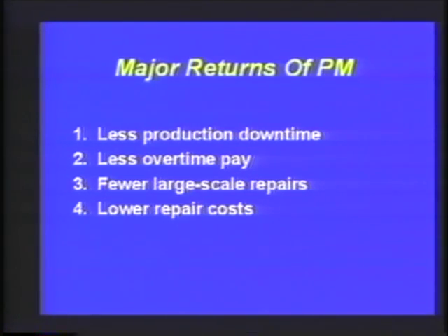If I'm in a firefighting, a reactive environment, I'm going to be spending a lot of time and money keeping equipment in top-notch operating condition. The PM program, I know what those costs are, and they, in many cases, are going to be less than those costs that are associated with a reactive or even a proactive maintenance operation.